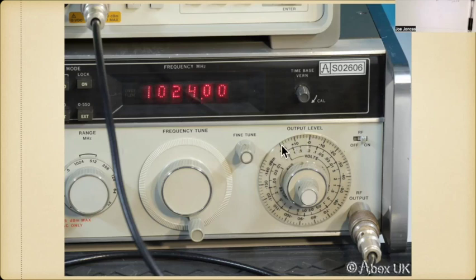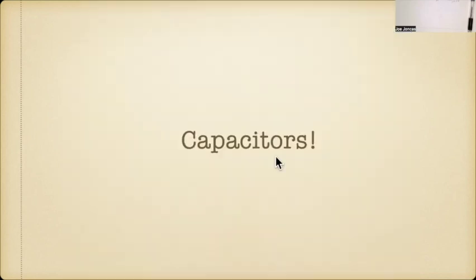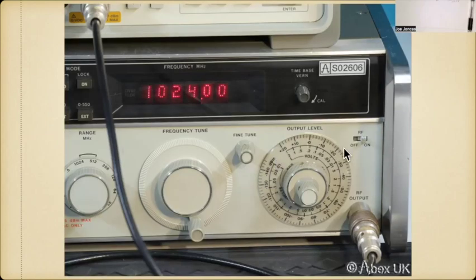If you go to plus 30 dBm, that's 1 watt. You go to 10 watts, it's plus 40. If you go to 100 watts, it's plus 50 dBm. A milliwatt is the reference.